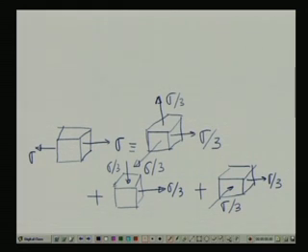However, in this case, if we just view from one side, it is equivalent to what? This particular one compressive, another tensile. It is just equivalent to something like a shear or distortion of the element that is taking place.